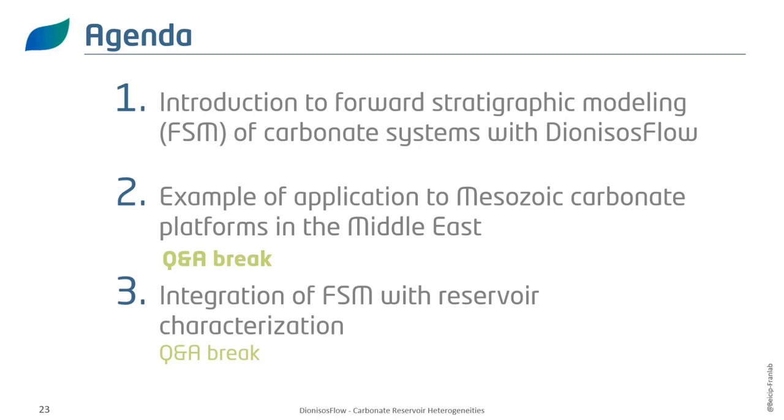You showed that we enter the wave system in the model, but what about the tidal influence? Is it included too? Okay, for the tidal influence, things are a bit more complex because tides usually work on a much shorter time frame. Remember, the time frames that we use here are thousands or tens of thousands of years. We have a tidal module that you can plug into the model, so you can integrate tides, but you have to be very careful when modeling tides. You need very good constraints to be able to calibrate this. Tidal influences act on a very short time scale, and these types of models usually simulate stratigraphy at a longer time frame.